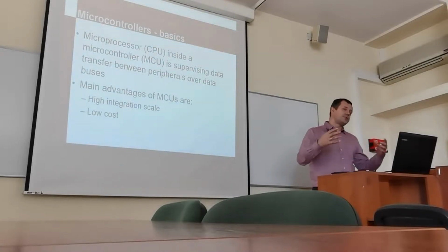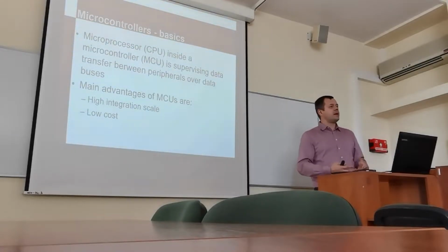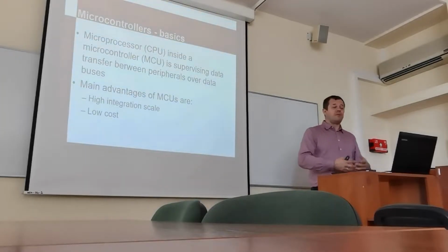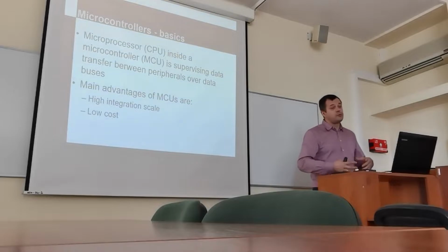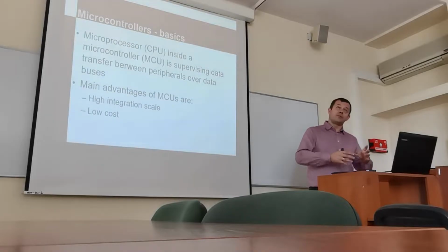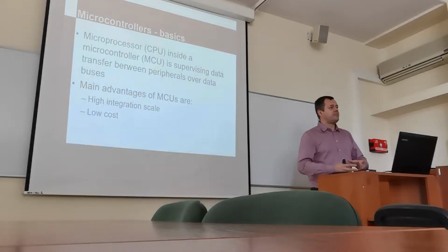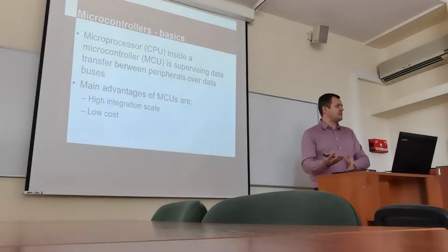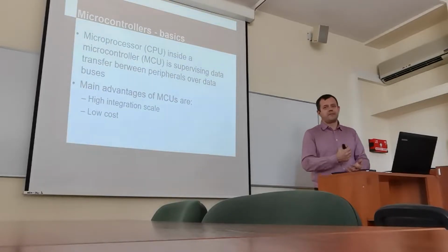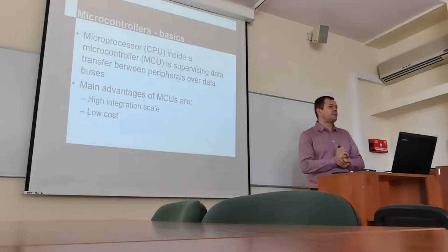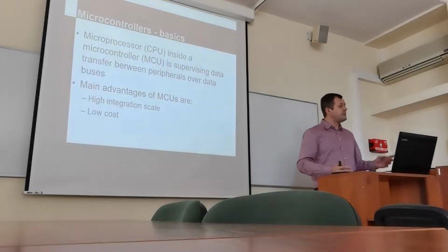But also, and I will stress it again and again, in case of the microcontroller, in case of embedded systems, microcontroller systems which are embedded in some larger devices, it's not about the performance of the CPU that matters. Of course, it is important to have a very fast CPU in some algorithms, but quite often the performance of the whole system is defined by a combination of CPU and peripherals, and the quality of the peripherals. So the quality and number of peripherals inside a microcontroller usually plays a very critical role in the performance of the whole system, not the CPU itself.